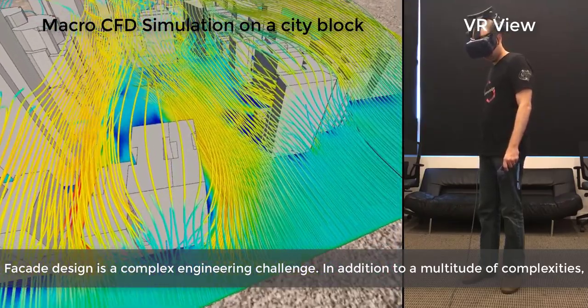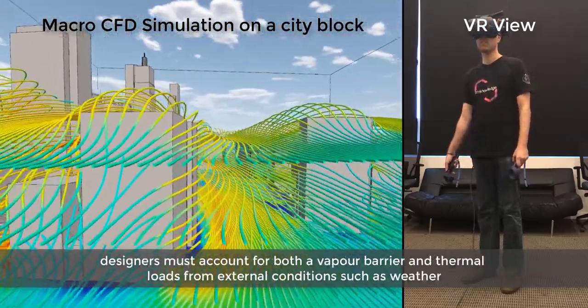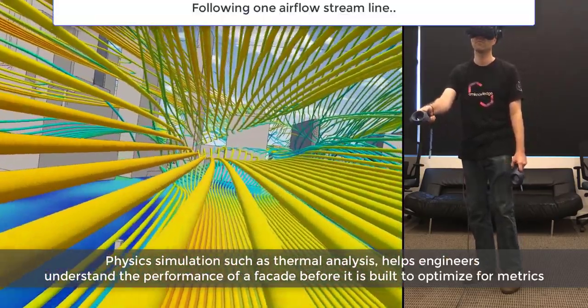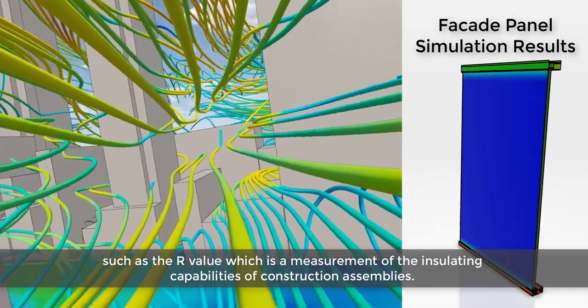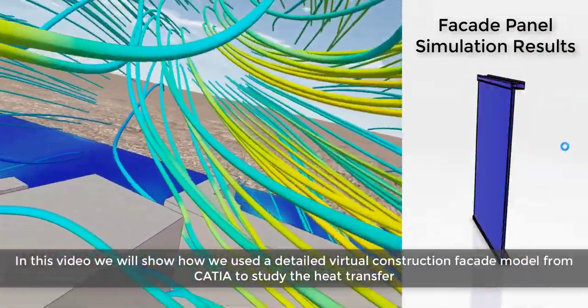Facade design is a complex engineering challenge. In addition to a multitude of complexities, designers must account for both a vapor barrier and thermal loads from external conditions such as weather. Physics simulation, such as thermal analysis, helps engineers understand the performance of a facade before it's built to optimize for metrics such as the R value, which is a measurement of the insulating capabilities of construction